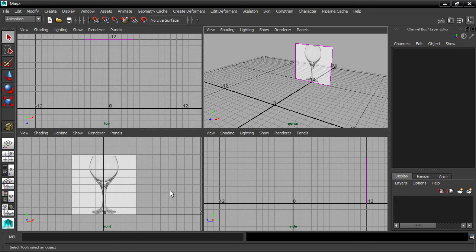I did some experimentation to prepare for this course, and I determined that the NURBS curves were going to be a better option because they're more reliable. The Bezier curves in Maya actually still have bugs. They were introduced years ago, but there's still some issues. Rather than run into those issues in this lesson, I opted to use the NURBS curves. And NURBS curves are probably a better choice for the lesson too, because they're probably less familiar to you. Bezier curves are pretty obvious. You probably use them in Illustrator and so on. So let's learn something new.